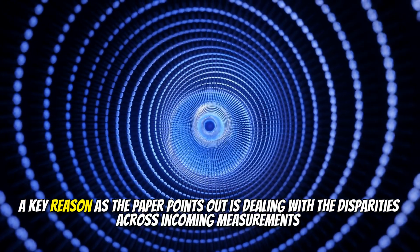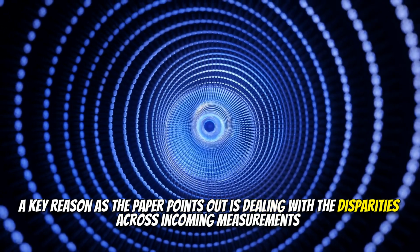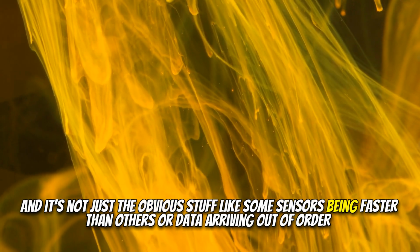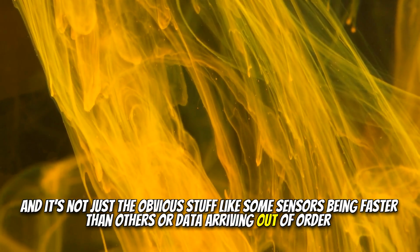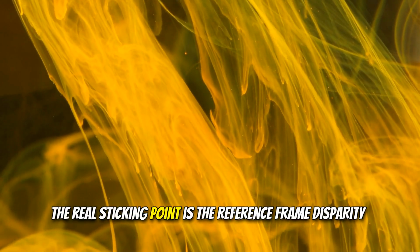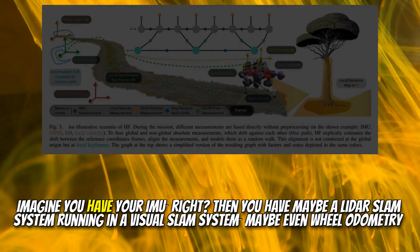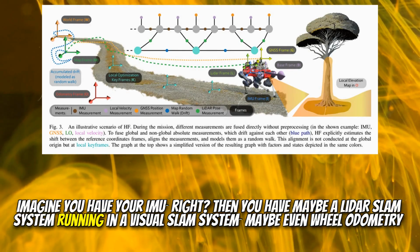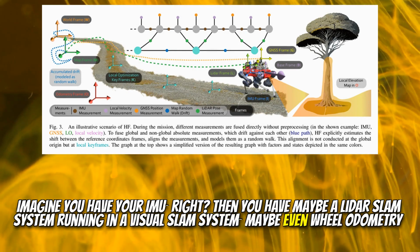A key reason, as the paper points out, is dealing with the disparities across incoming measurements. And it's not just the obvious stuff like some sensors being faster than others or data arriving out of order. We have decent solutions for those now. Yeah. The real sticking point is the reference frame disparity. Imagine you have your IMU, right? Then you have maybe a LiDAR SLAM system running. And a visual SLAM system, maybe even wheel odometry.